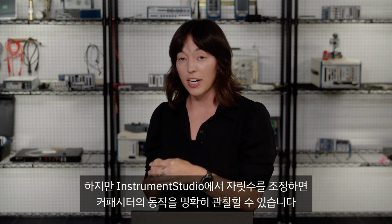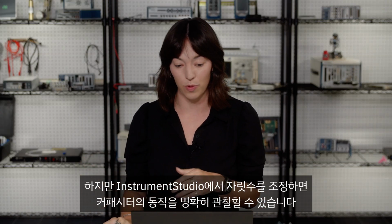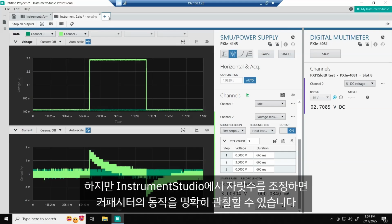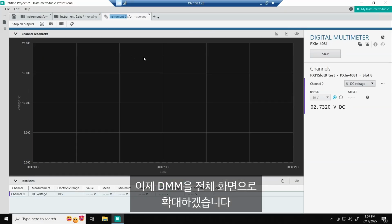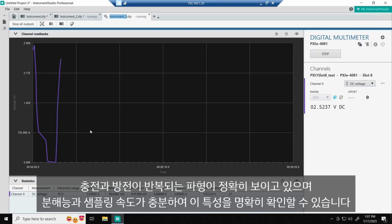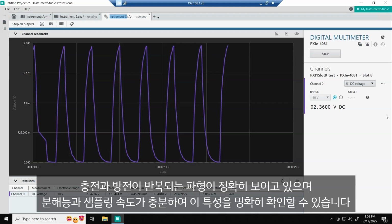But with our DMMs and changing that resolution in InstrumentStudio, you can actually take a look at what's going on with the capacitor. So I'm going to put our DMM into a full panel. And you can see here that we're actually seeing our capacitor charge and discharge because we've got our digits of resolution at enough speed that we're getting enough samples per second that we can actually see that characteristic.